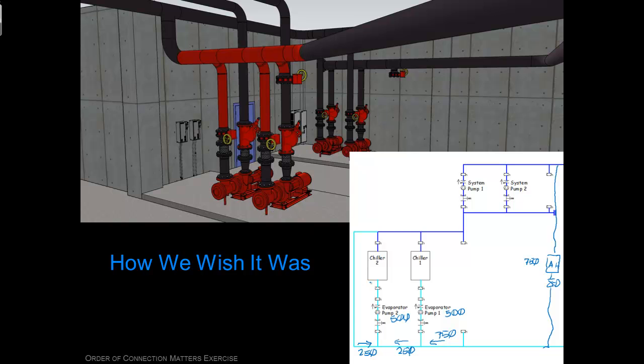There's another interesting difference between a plant with the bypass here and a plant with the bypass here that I'll do a second video on in the next day or two, or probably more like a week. But for the time being, what I hope you learned from this is, A, how to go about making the system diagram, and B, that subtle differences in how something's piped can make a huge difference in how a plant's going to work.